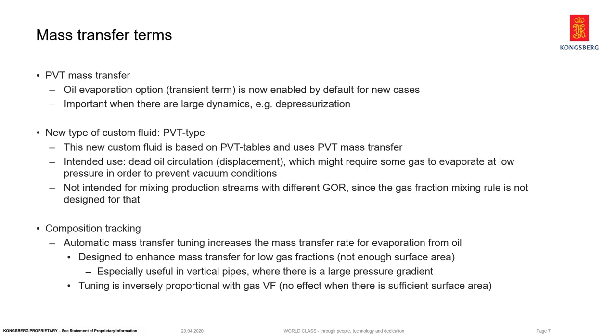So we're not changing the model, we're just changing the default setting if you're creating a new case in LedaFlow 2.6. And this is important because if there's large dynamics in your case, like for instance in depressurization, this will change the results quite a bit. So it will improve the results by having more gas evaporate from the oil phase. That's why we're mentioning it here.